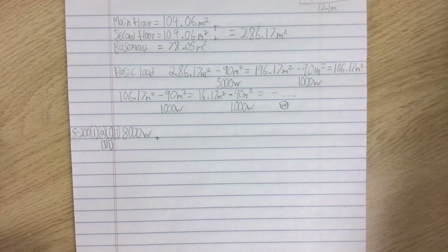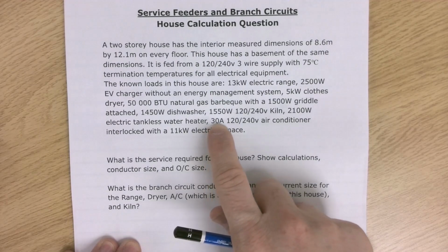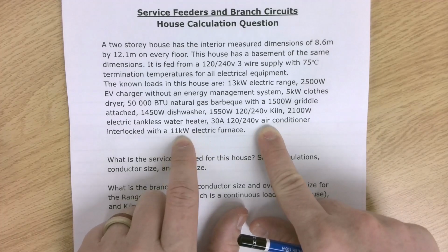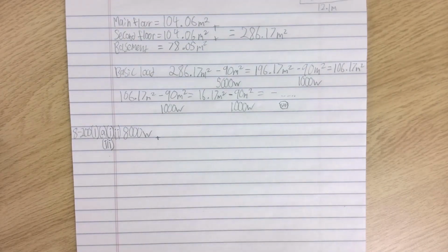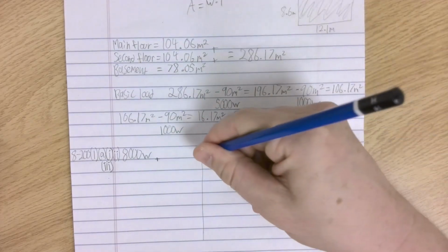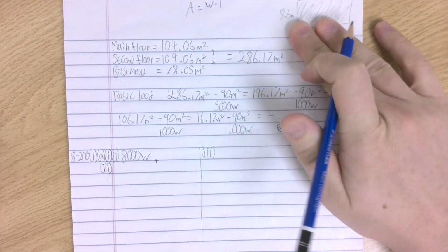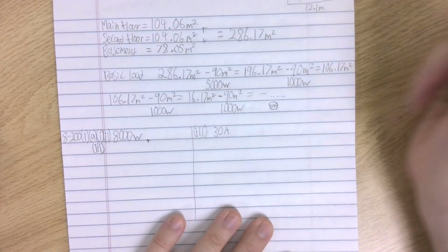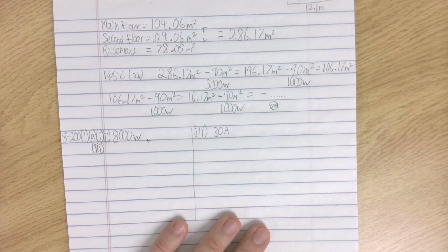And so we're not really sure which one's greater, though, because we don't have a wattage for the air conditioner, for one. And I don't know what Section 62 is going to tell me to do with this 11,000 watts of the electric furnace. So I'm going to draw myself a little divider here on my page. I'm going to remind myself that this is I. And I'm going to take 30 amps. I'm going to figure out my wattage of the air conditioner first, because that one's a bit more straightforward. Once I have my wattage, I know the demand factor is 100%.